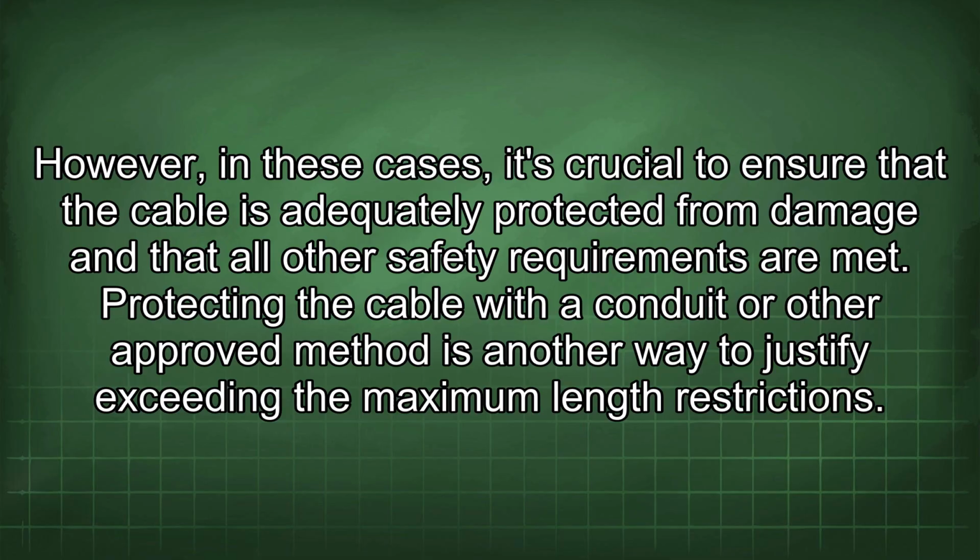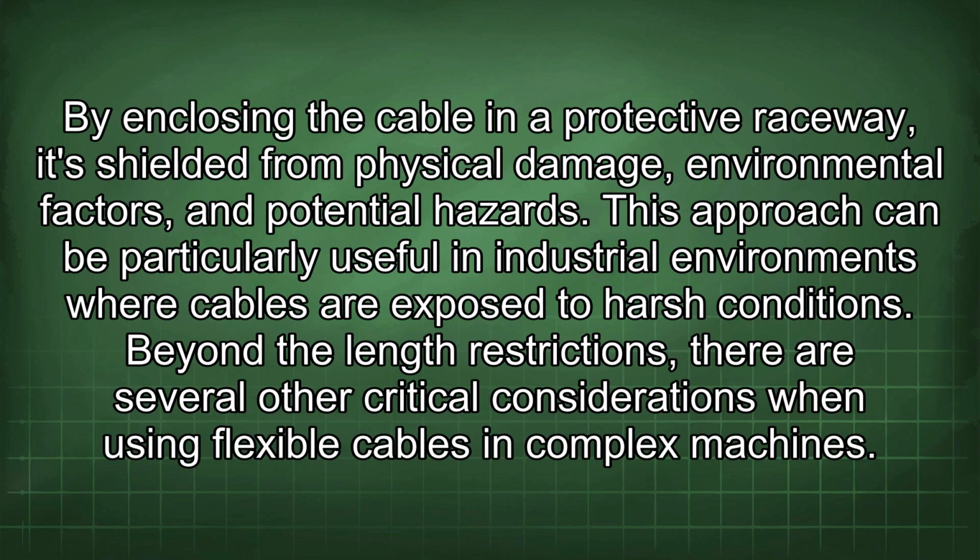Protecting the cable with a conduit or other approved method is another way to justify exceeding the maximum length restrictions. By enclosing the cable in a protective raceway, it's shielded from physical damage, environmental factors, and potential hazards. This approach can be particularly useful in industrial environments where cables are exposed to harsh conditions.